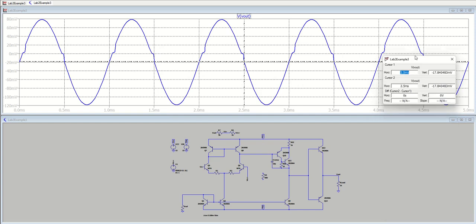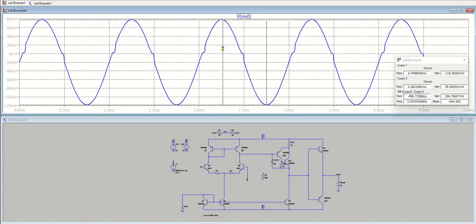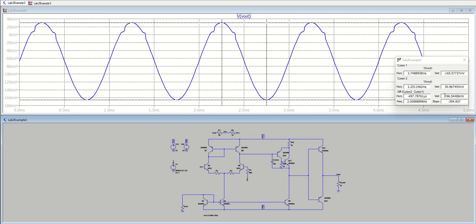So now what I'm doing is I'm just measuring the sinusoid, which I'm getting 196.9 millivolts. So by putting this compensating resistor into the circuit, it should get rid of any excess noise. So this value should probably go down, and it does. It dropped by maybe 0.4 millivolts.